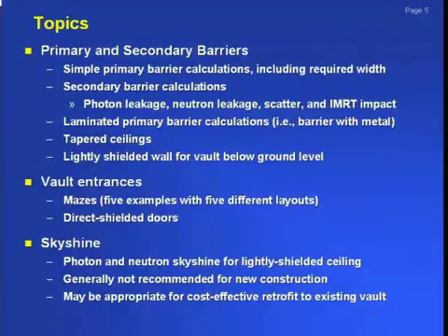I would recommend that if you are doing new construction, you do not shield for sky shine. But what you will find is you start doing these with retrofitted construction. Many older vaults were built with basically very minimal ceilings. So you do have to do a sky shine calculation at that point. That is really effective and used primarily only for retrofitted vaults.